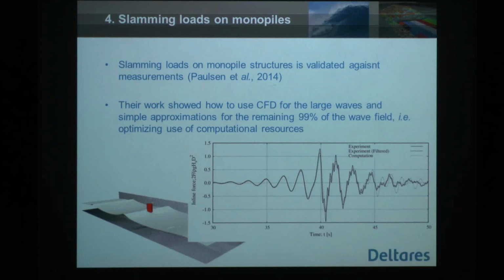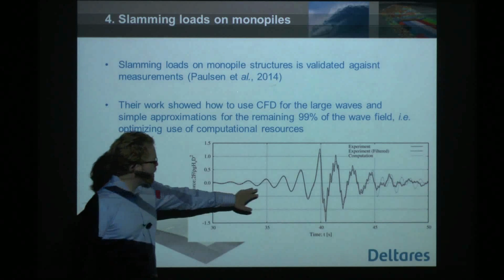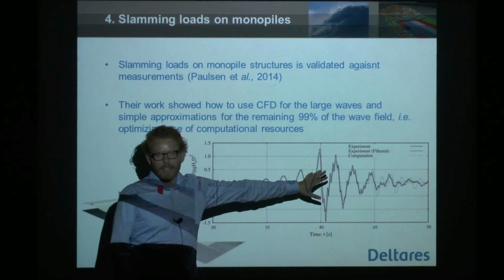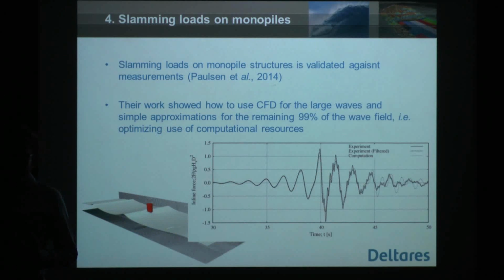So slamming loads, Poulsen et al. have been using CFD modeling to validate OpenFOAM for this, so we can now confidently use the modeling. And what you can see here is that in the laboratory they created a focused wave.